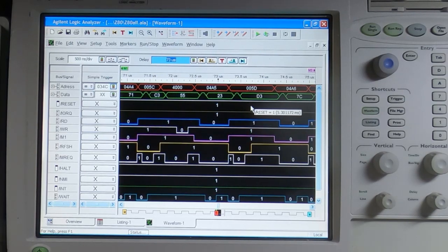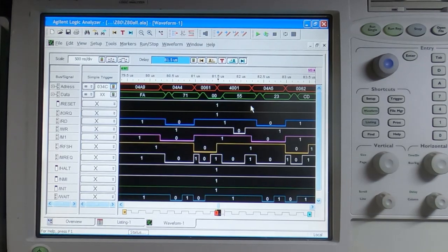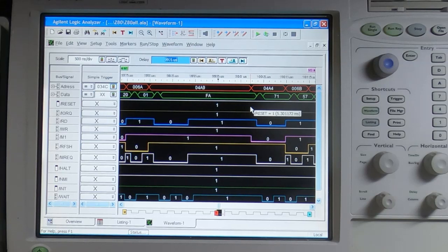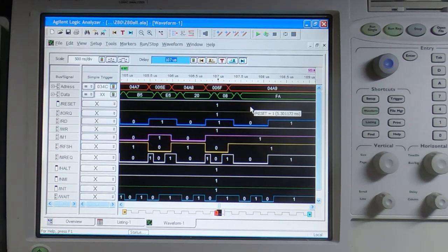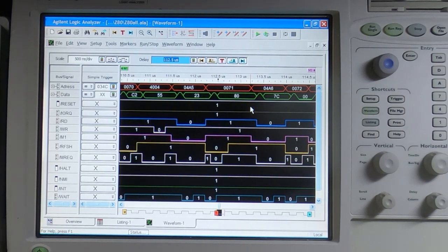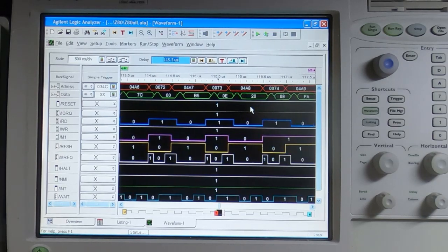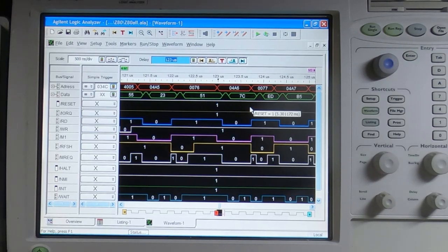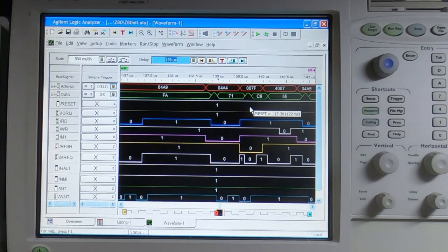and what's odd here is, one thing I didn't mention is when the processor starts up, it loads a value into the Z80 stack pointer of EE20, and it's performing calls here and returns, but we're never seeing anything like that address appearing on the address bus.